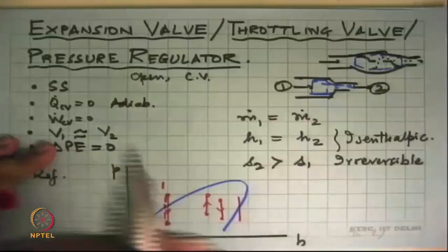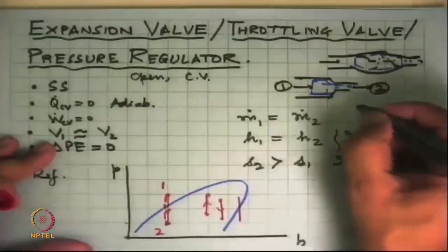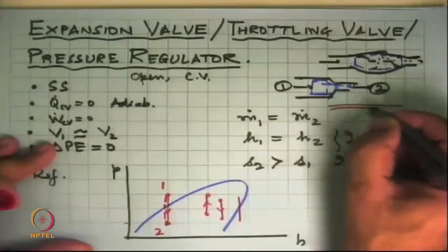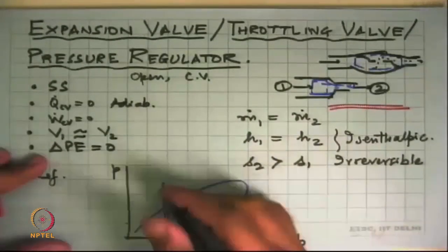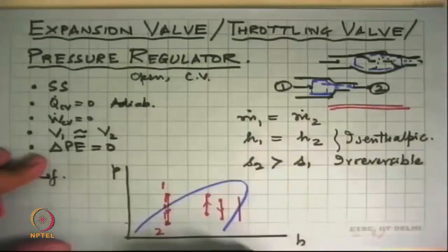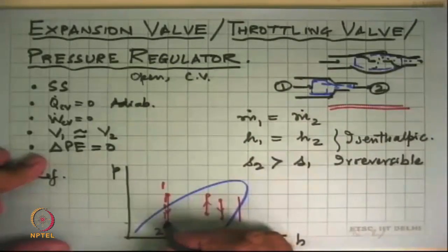And that can be done either through a valve, or we put the refrigerant suddenly through a very narrow tube where there's a very large pressure drop. That's all it does. In the process, a subcooled liquid becomes a saturated state and the wet mixture that you get here.